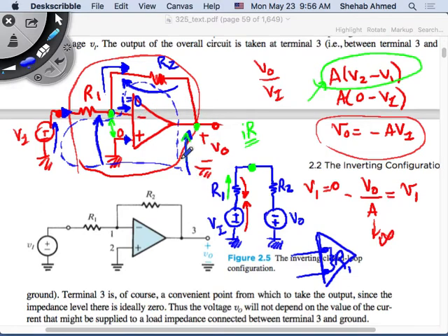Here, then I can do Kirchhoff voltage law around which loop? Here I have a voltage here, and I have a voltage here, and then this node's voltage is actually 0. Right? Which means that V output plus this voltage is equal to 0, or V output is equal to the negative of this voltage drop. So what is this voltage drop? This voltage drop is the current flowing from the input sensor and then up through this branch multiplied by this resistor value, right? So first, it's important to be able to calculate the current flowing in.